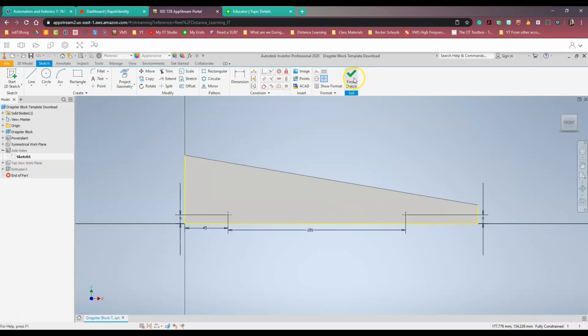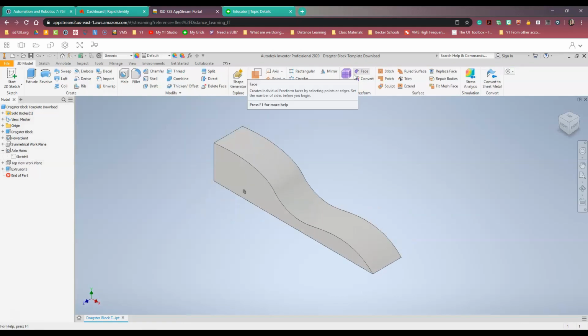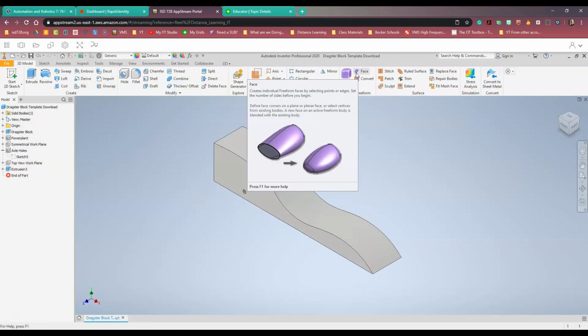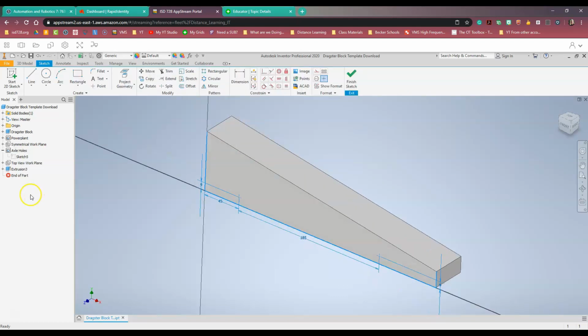So let's see what happened on my 3D part. So I still moved that 15 millimeters, but I can't see my axle hole in the front yet. Let's hover there. It moved closer, but it didn't move enough. That must mean I have to change it a lot. So again, I'm going to go back and I'm going to edit this sketch with either a right click on my mouse or a two-finger click on my trackpad. I'm going to edit the sketch.